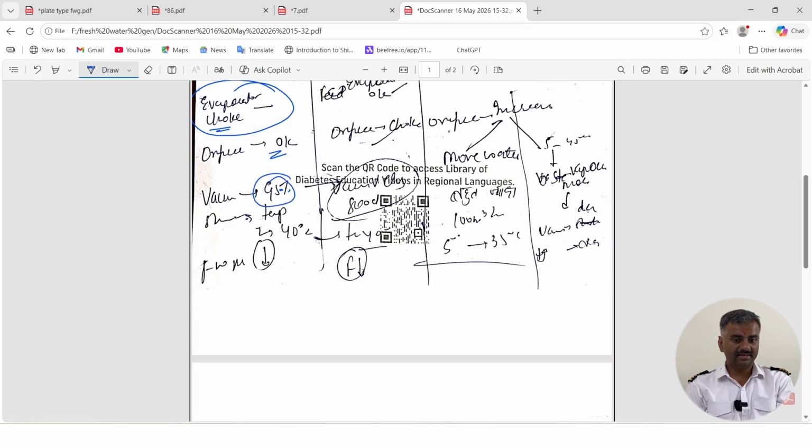And with no vapors in the cell, the cell temperature will also be optimum, 40, 45 degrees centigrade. But your freshwater production will drop in this case. Initially, I had a perception that the vacuum has to drop and the cell temperature has to rise, and only in those cases can your freshwater production drop.